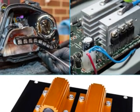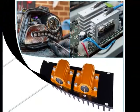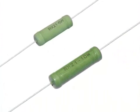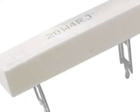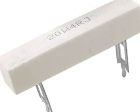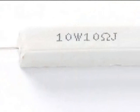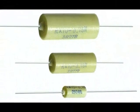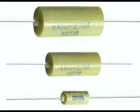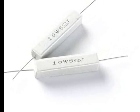Since the wire used in the coil resistors is coiled, the property of self-inductance is created. In this way, in addition to resistance, there is also inductance. This inductance causes phase shift, especially in larger resistances, in AC circuits and at high frequencies. Therefore, the total impedance, Z, is the combination of the apparent DC resistance and the series inductance. Impedance, Z, is the combination of the effects of resistance, R, and reactance, X, in series with it in an AC circuit.